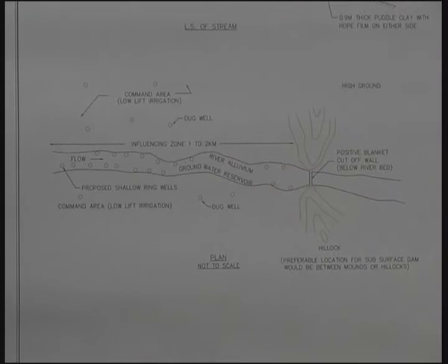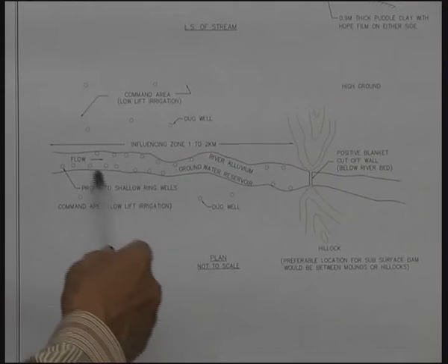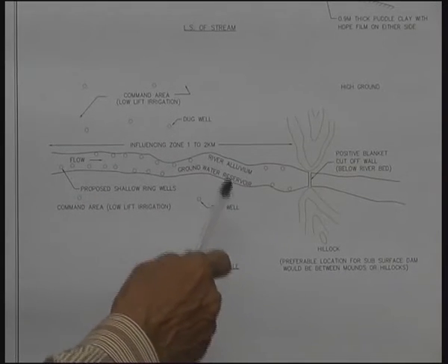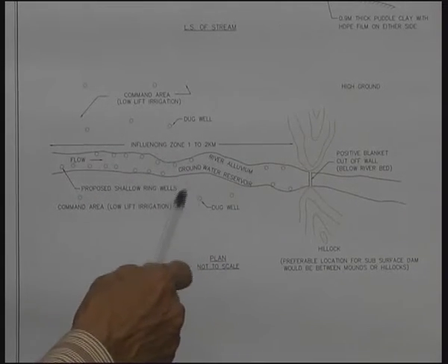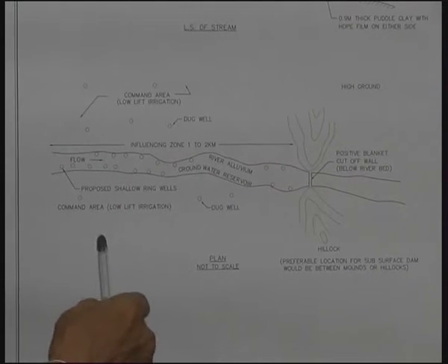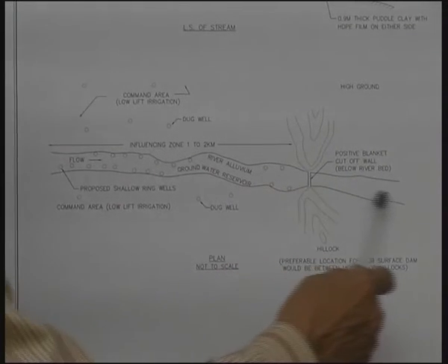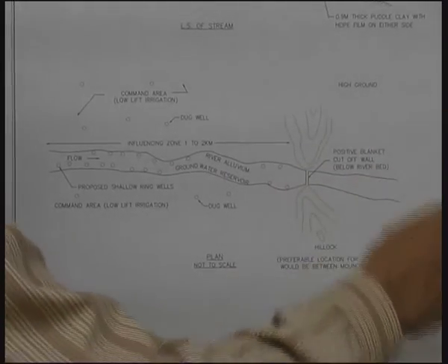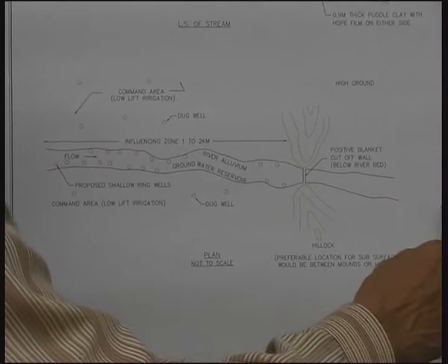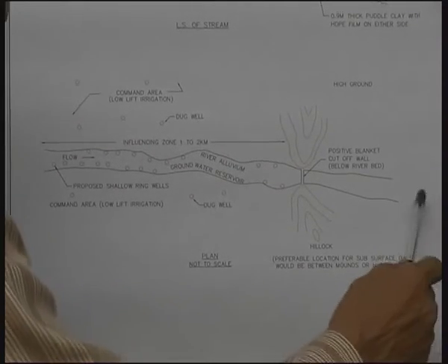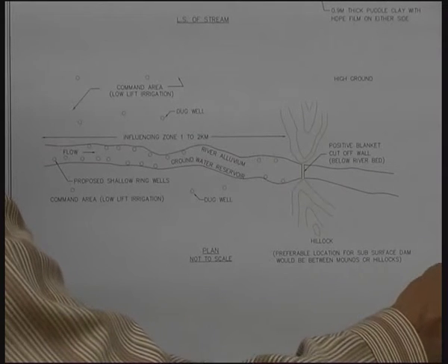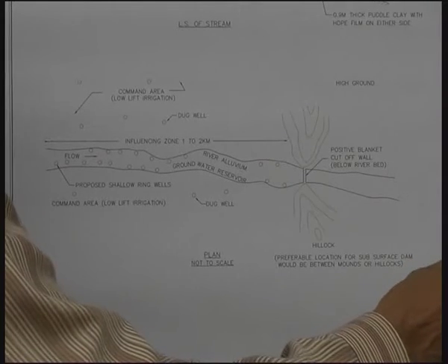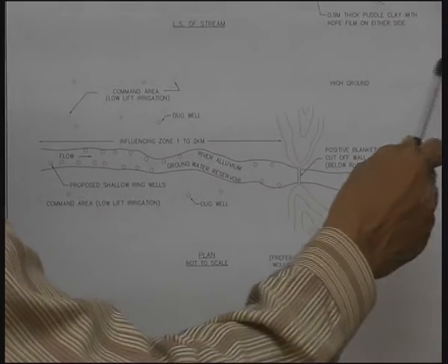But usually in most of the watersheds, the upstream watershed would be without any big basin draining into it, whereas as we go to the downstream side, a number of tributaries would be coming and joining, and there would be a bigger basin as we go towards the downstream side, and there would be a good amount of groundwater on account of draining a much wider and bigger basin.